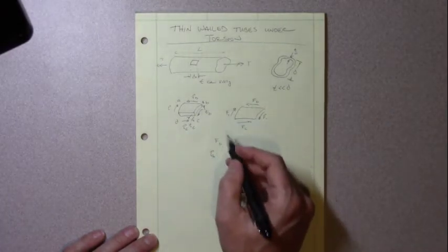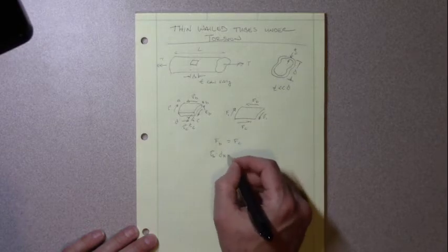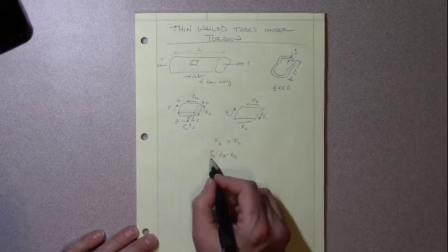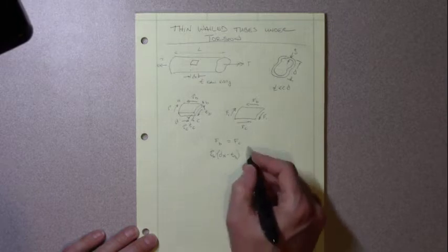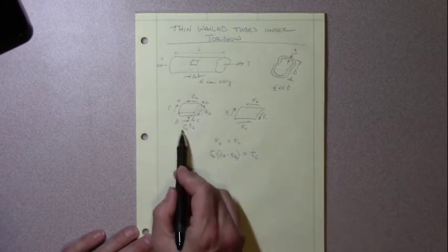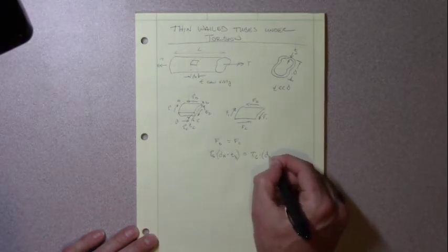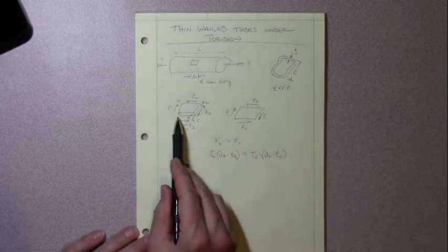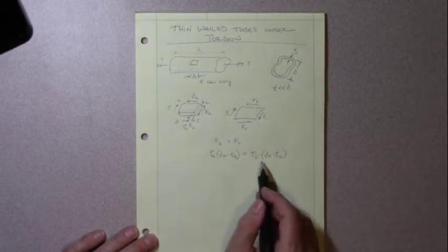The area on that face is dx, the length, times its thickness, t sub B. So we have shear stress times this area, and we end up with a force. F sub C is the tau on face C, times our area, dx, times the thickness of that surface C. So again, tau C times that area gives us that force.